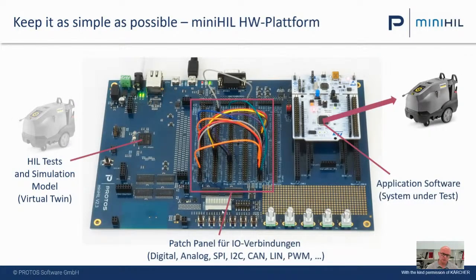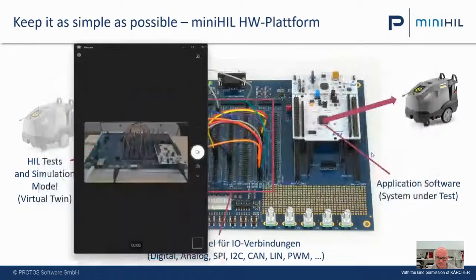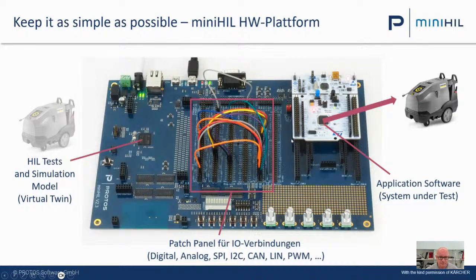How do we do this? We have a very simple hardware platform for hardware-in-the-loop tests. It's a small platform. I can show you that. I have here my demo system. So it's as big as a piece of paper. Focus is to test the microcontroller with the complete software stack as it is at the pins of the microcontroller, so on pure signal level.